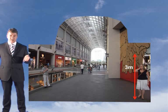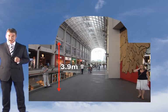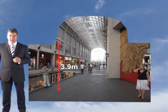However, in this case, it's also desirable that smoke should not be allowed to enter any shop unit. Now, the highest shop unit is 3.4 metres. So with a clearance of 0.5 metres, we need to increase this clear lay height to 3.9 metres. So that's what we've got to maintain, 3.9 metres.